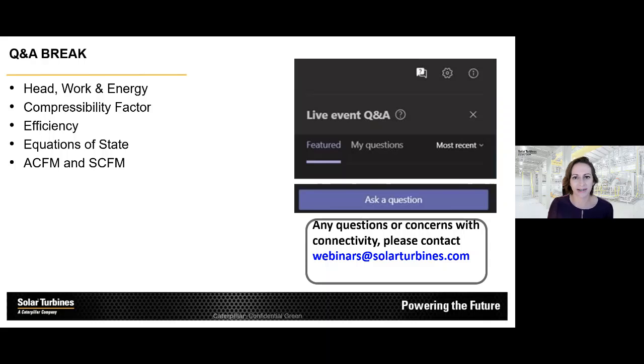So one that I think pertains to this content is from Ryanto from North Oil Company. Thank you. Does non-dimensional curve of centrifugal relate to compressor impeller design, Rainer? We're actually also getting to that in the next section, but yes, the non-dimensional, for example, the head versus flow, non-dimensional head versus flow characteristics depends on the aerodynamic design of the compressor.